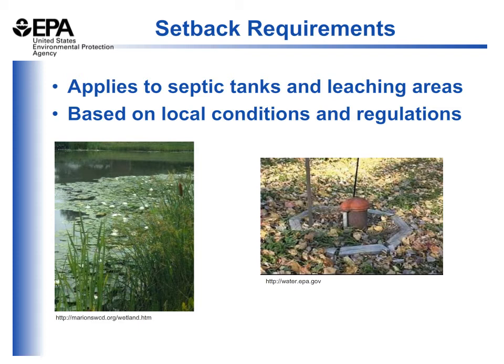On the last slide, we talked for a moment about environmentally sensitive areas. One way that septic systems are managed to protect these is to apply setbacks. A setback is a minimum distance that a septic system, or one of its components, can be located from a surface water, wetland, stream, local private well, steep slopes, or other environmental factor that plays into the design of the facility. These setback distances can vary from location to location across the country. They're based on local conditions and on local health regulations promulgated either by the tribe or local community, or sometimes at the state level.